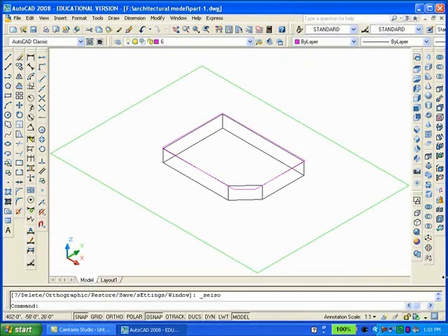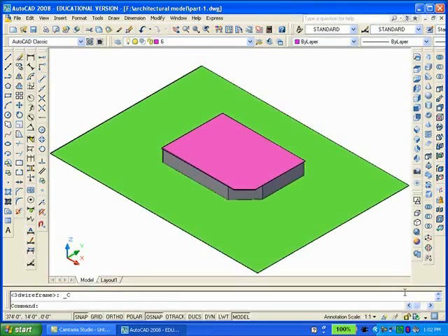After closing the polyline, move into the southeast isometric view. Since the building is 25 feet tall, we want to extrude the roof 1 foot downward. So I'll select the roof profile and extrude it -12 units down, typing 0 for the extrusion taper angle. As you can see, this forms a 12-inch roof slab extending 12 inches out from the building.